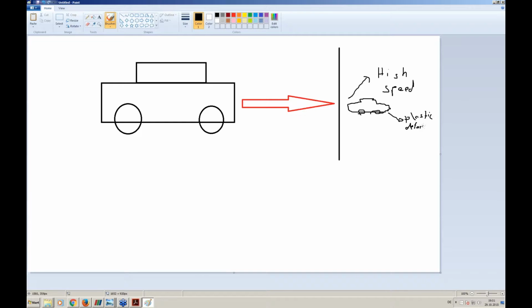But if we have a very low speed, and maybe some of you know that there is a kind of law that up to, I think, 3 kilometers per hour, when you have a really small impact, the front bumper of the cars should not be destroyed. This is because with these low speeds and low energies, we have only elastic deformation. Nothing will crack, nothing will be destroyed later on, and this is something we can simulate.